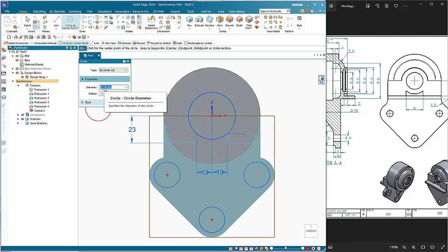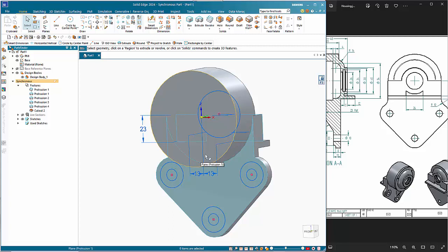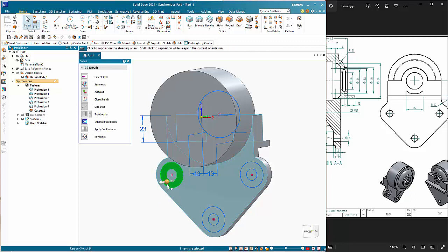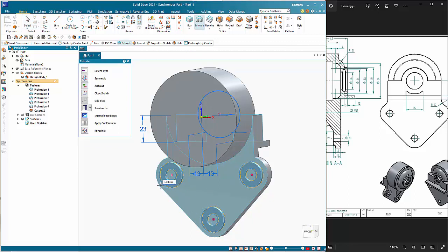And then the holes are 10 mil. And they can be placed there. So escape out, rotate it around, unlock the plane. So I'm going to do this in one move. So click on the first area, Control, select for the second one and the third one, and the depth on these are 3. So if I just click on the arrow, type in 3.